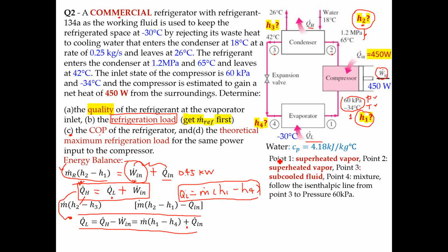So these two parts, when you have a commercial refrigerator and this refrigerator is generating heat at some heat transfer rate, these two parts of heat generation is the total refrigeration load we need to provide. That's something we need to explain to you, because later if you look at the solutions, you will really easily get confused about that. So are you all clear with this part? Good. Okay, so I think we can continue to the practice of that one.